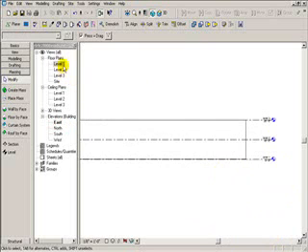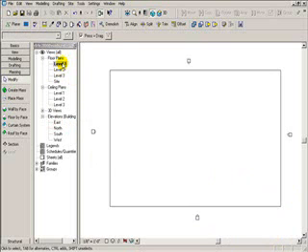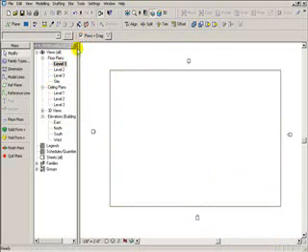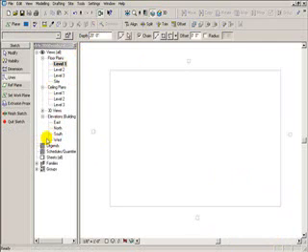Now the first thing I want to do is make an extrusion that goes all the way through the center of my building. So I'm going to select the building and then edit. Then I'm going to go void form and void extrusion. I'm then going to sketch a rectangle.